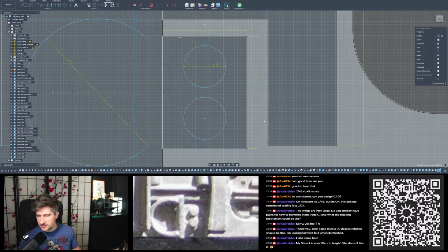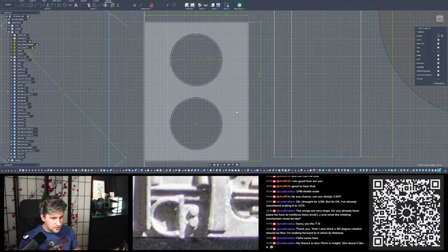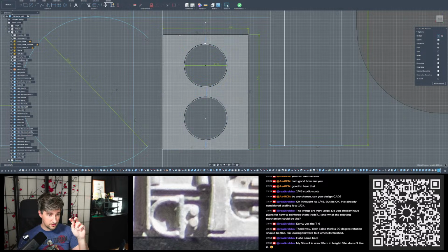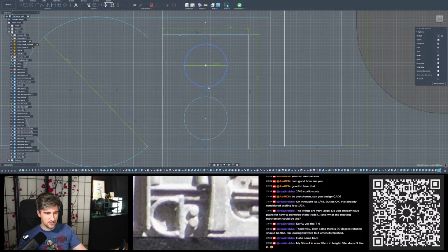I don't know if you can see that on screen. And now I can place a constraint that all those 3 should be the same length. And with that, I get the same spacing from the screws to the outside edges and between those 2 screws.